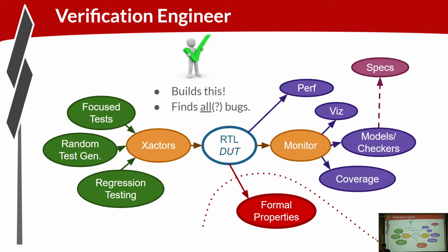On the other side of the RTL model, you are checking the outputs to make sure they're correct. So you need to monitor the outputs. The monitor is basically in the opposite direction. It's taking the pin level details and up-leveling that in some fashion. Other tools connect at the interpretation of the output signals.